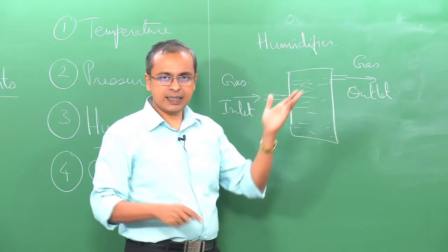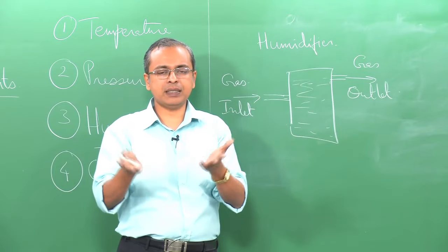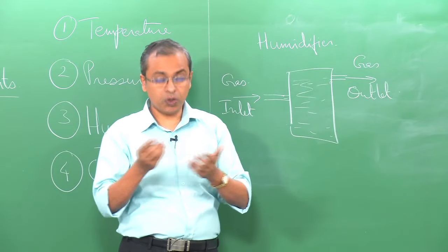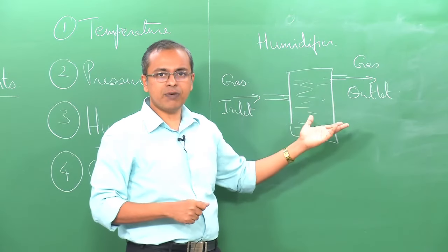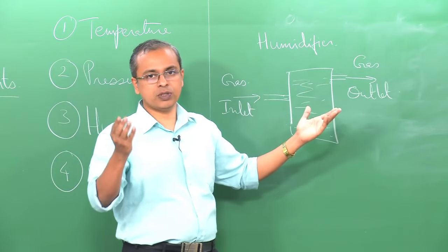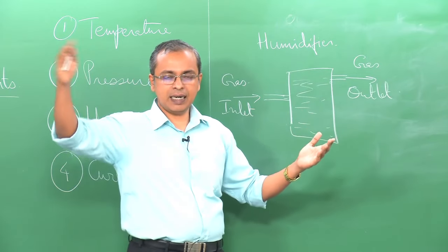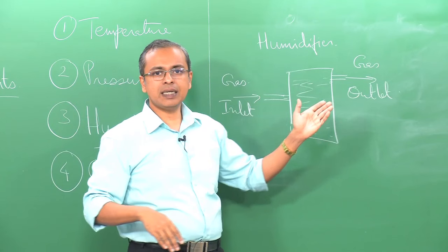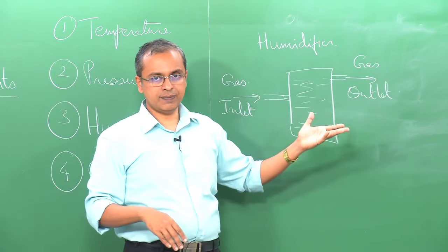And if you go to 100 degrees C, the carrying capacity of the gas goes up with the temperature. So, at 100 degrees C, the same 1 liter of air can carry much more moisture. So, if you go from room temperature to 50 degrees C, 70, 80, 90 and 100, as you keep raising the temperature of the gas, it can carry more and more moisture, right.